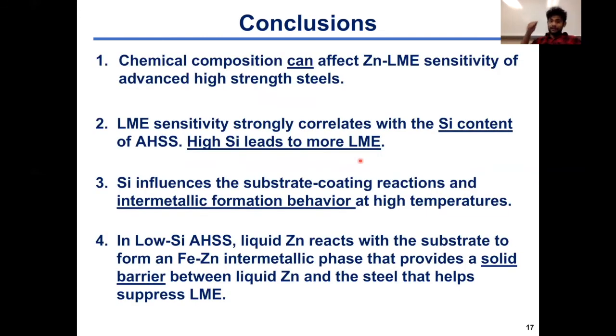So in conclusion, chemical composition can definitely affect LME sensitivity, as we had seen in this presentation. LME sensitivity strongly correlates specifically with the silicon content of an AHSS. High silicon content leads to more LME. We didn't find a correlation with the carbon and manganese content of an AHSS. Silicon influences the substrate-coating reactions and intermetallic formation behavior at high temperatures. Recall those coating microstructures that I had shown you. In the low silicon AHSS, we saw that the liquid reacts with the substrate to form an Fe-zinc intermetallic layer that provides a solid barrier between our liquid zinc and the steel substrate, which helps suppress liquid metal embrittlement.